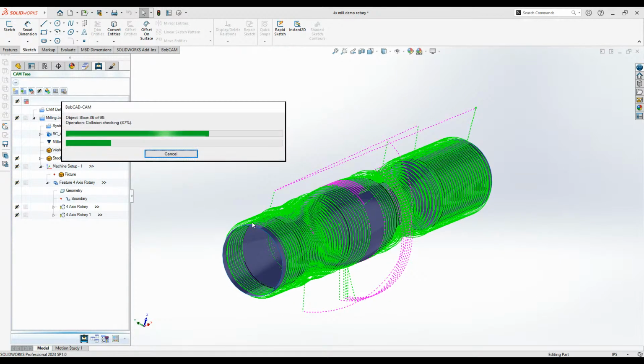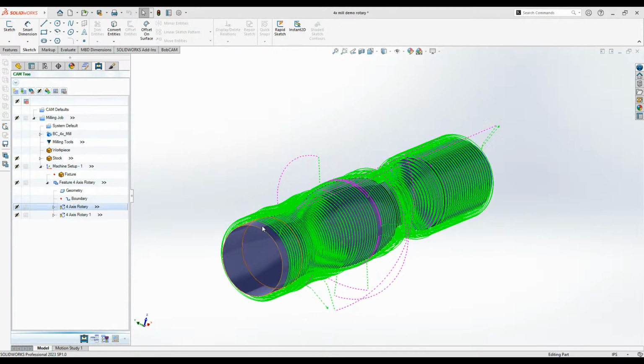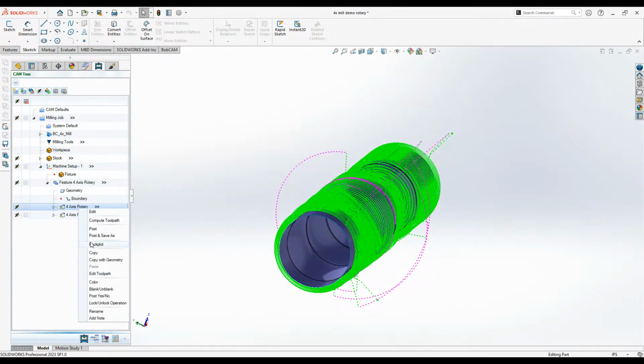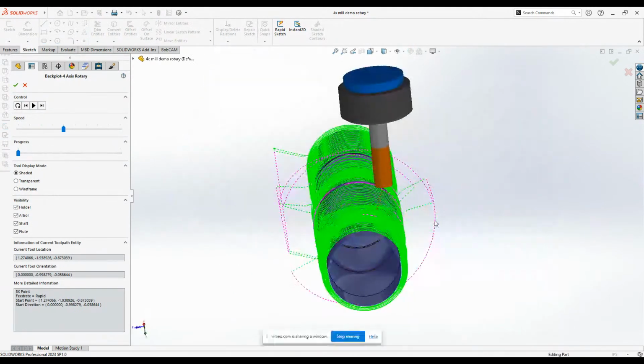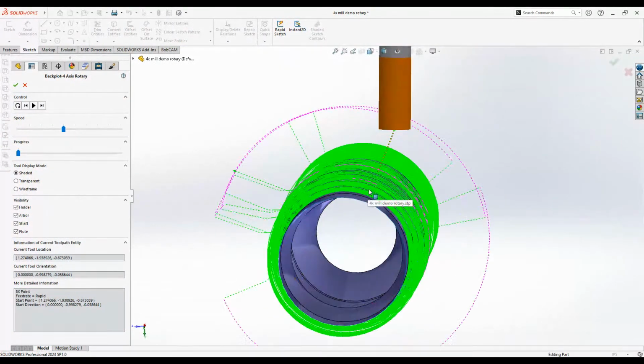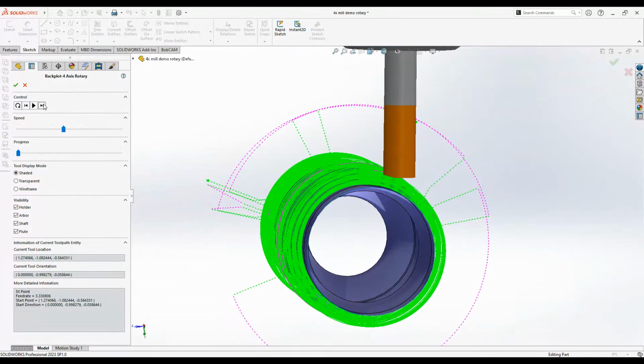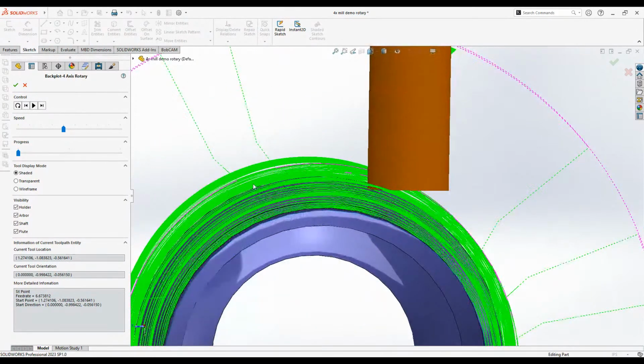And so the tool will shift over to the side of the stock or the side of the rotary axis automatically. And then it will be stationary in the Y axis. It won't move back and forth. You'll see that the tool is a 1/2 inch over. So when it's being machined and the stock is rotating, it's going to be rotating around that way and milling with more of the side of the tool instead of going straight down to the rotary axis.